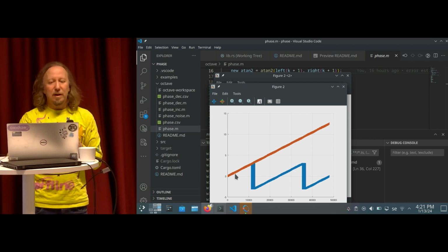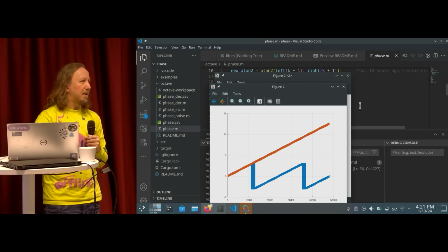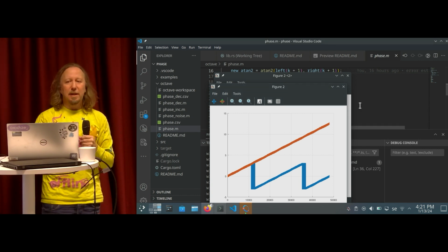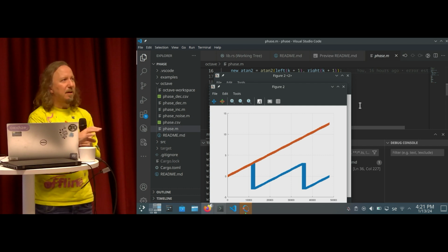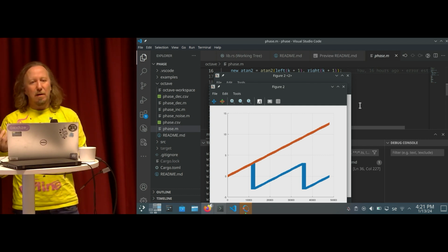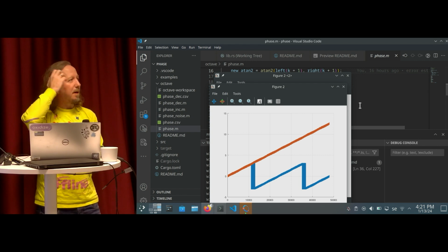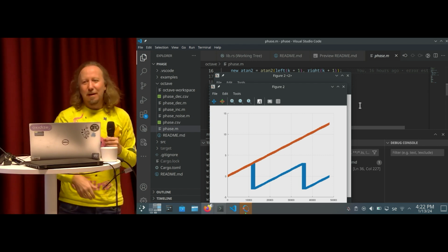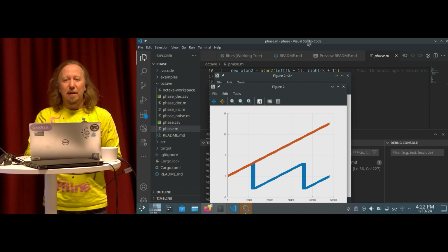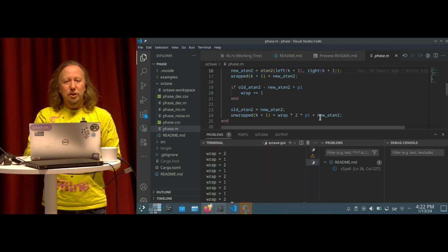On the average, if we make a bit of low-pass filtering here, it would look perfect again. So that means that it's really robust. 25% noise would be approximately 2 bits. If you are sampling with 2 bits, then you will get that bad signal to noise ratio. But we can push it.